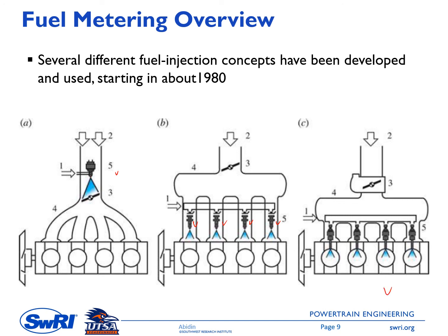C will have even better transient response compared to B, because the fuel is injected directly inside the cylinder. So B and C are maybe slightly similar in terms of complexity, but C will require a more expensive injector because it is injected inside the cylinder. We will need a good injector to make sure that the fuel can evaporate faster than with PFI.